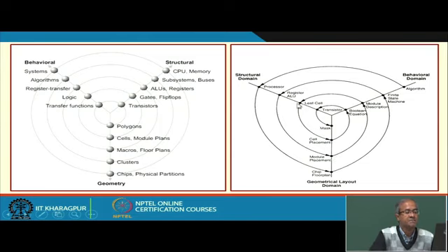Again you go to description like gates or some cells, as we will talk about later. Then again how to place these cells, then again low level, finally transistor up to the layout mask. So, you see if you follow this kind of helix approach from the outermost circle to the innermost one, you are actually following the exact process which typically we follow during the design when we go through the so called top down design approach.